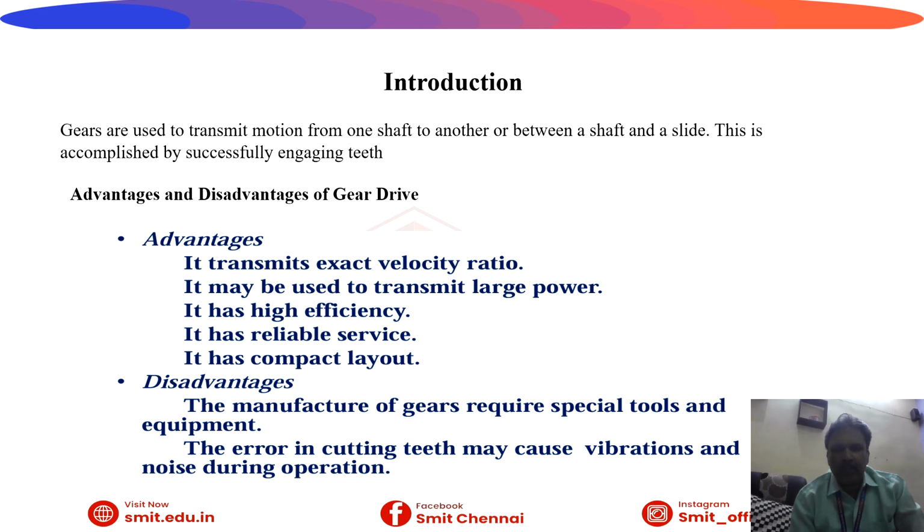That is the introduction part of gear. It is used to transmit motion from one shaft to another shaft, or between a shaft and a slide. This is accomplished by successfully engaging the gear teeth. As you are all aware, it is a transmission of motion from one shaft to another shaft. For that purpose only we are using gears. So what are the advantages? It transmits an exact velocity ratio. It may be used to transmit large power. It has high efficiency. It has reliable service.